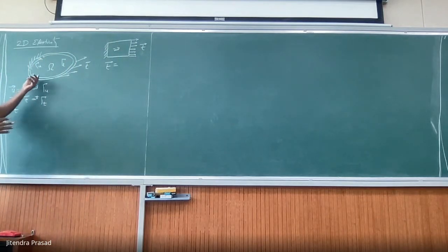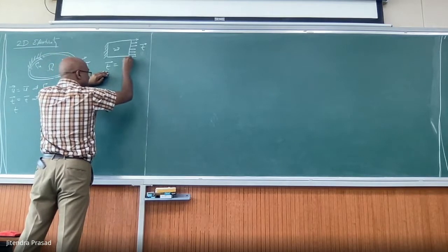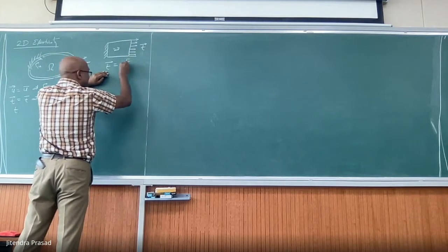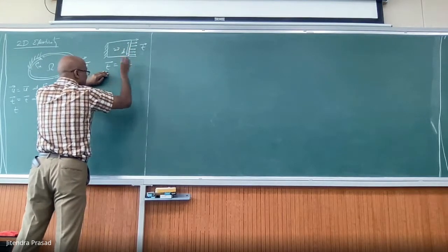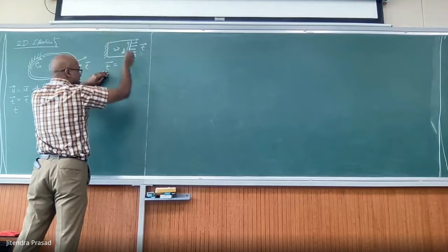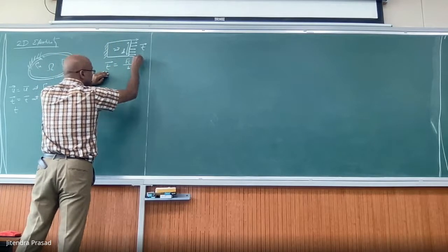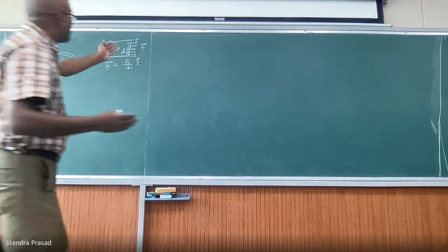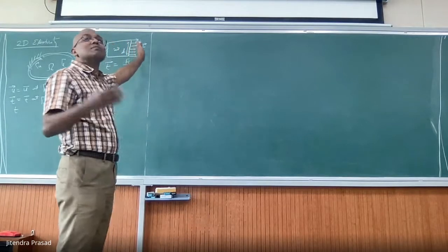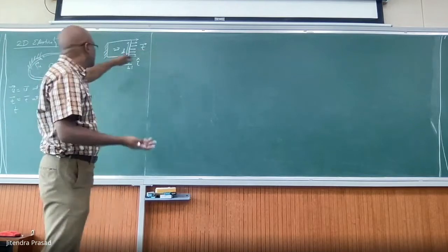The traction has the same unit as sigma basically. So T is basically the total force in the x direction divided by area. Let us say from here to here is b, so you write divided by b, and 1 is the thickness. So traction is nothing but the net force at that surface.